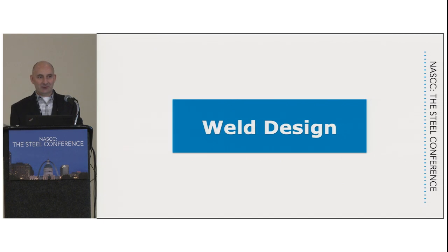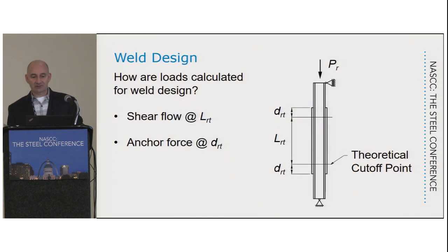And it really kind of turned a light on when I did exactly what I told you to do, which is just do a normal W14x90 column and do everything I just said, and you'll end up with very similar results to what you would get with the AISC specification equations.